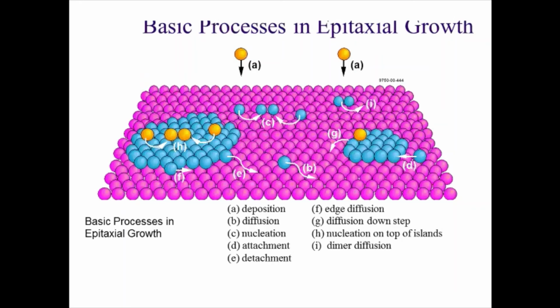That is why the thermodynamic calculation, or the kinetic parameter determination for the epitaxial growth, a prior theoretical calculation, is necessary, and that will avoid so many difficulties during the growth. So on the surface, after pyrolysis of the species, the related atoms move to the surface of the substrate. These atoms form a dimer or a trimer and form clusters. And once these clusters join together and form a layer, it means complete wetting is done. In that case, layer growth occurs.